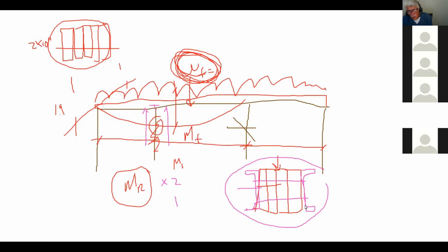So one of the mistakes that people make is they don't jack up their column. So this way, when they put the steel on it, you have to load the column. How do you load the column? By jacking it up. And then when you attach the steel to it and you remove that support, the steel and the wood now work together, and of course, we would have to calculate the moment of inertia required and all that.